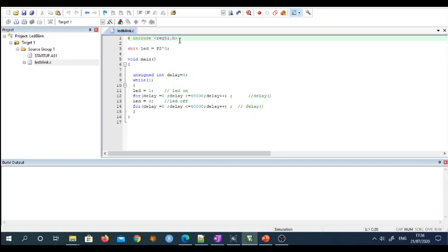performing various operations in 8051 are included in this editor. So that's why this include statement is very important, and it is similar to the include stdio.h that we normally include in C environment. So it is as good as we are including the library of 8051 microcontroller. This is the sbit command which I have explained already to you. The sbit command is used to define the individual ports of the microcontroller. So here I have used a variable LED which will be assigned to port pin 2, 0 or P2.0.